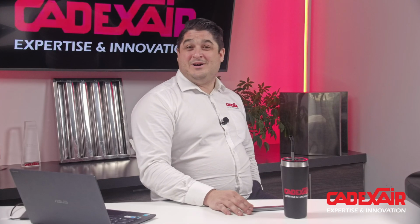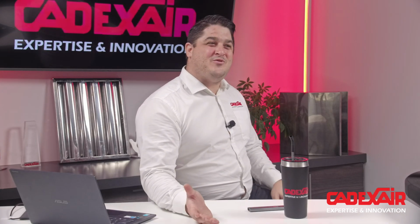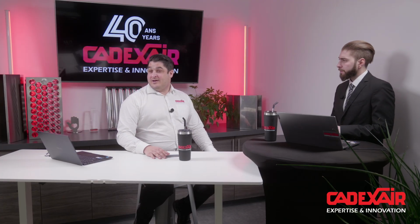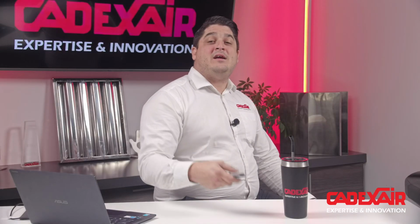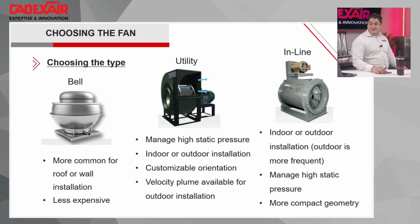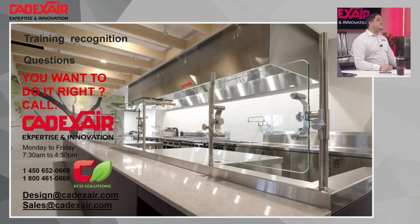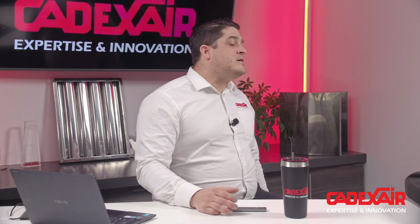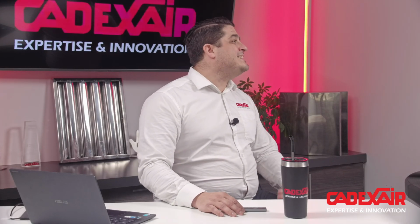Perfect. Another question. I don't have space outdoors to install the exhaust unit. Is there a way to install the exhaust fan indoors instead? Yes, for sure. Sadly, it was in our training, but we had too much material, so we had to cut it back. We have a model of fan, an inline fan, that can be put inside. As soon as the fan is listed as per UL 762, or has a UL 705 power ventilator tested for cooking operation, the fan will be allowed. So the inline fan exists to be put inside of the building.